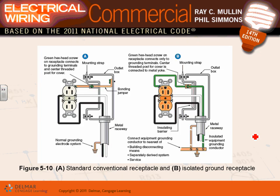Here's what you have. When you have receptacles, guys, you have two types. I want to bring to your attention one little bonding jumper right here. Can you guys see that? Where is it here? It does not exist. That's the only difference between an isolated ground receptacle and a non-isolated ground receptacle. In a non-isolated ground receptacle, they bond the grounding conductor to the box. Can you guys see the bonding here? Into the box, into the conduit. That's what the receptacle you're looking at is designed for.